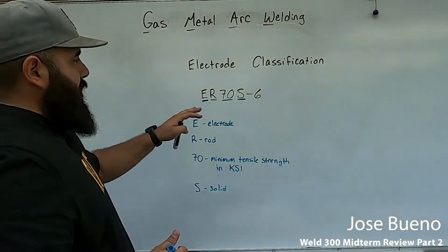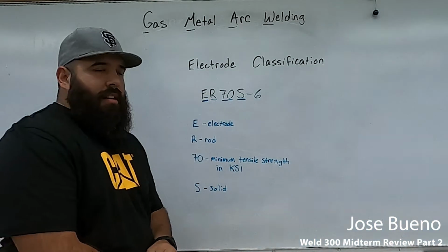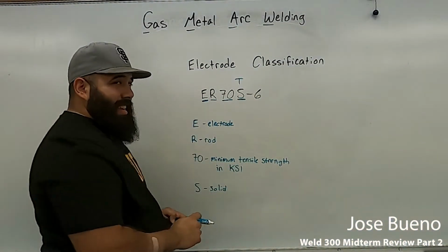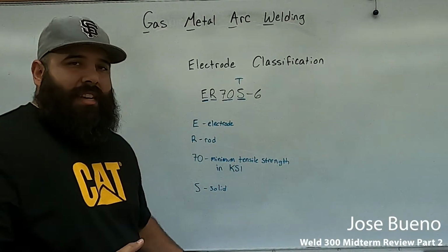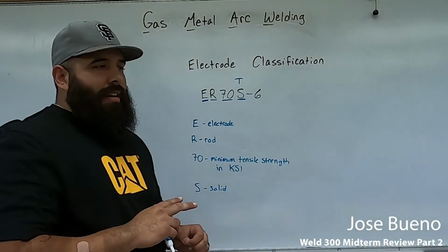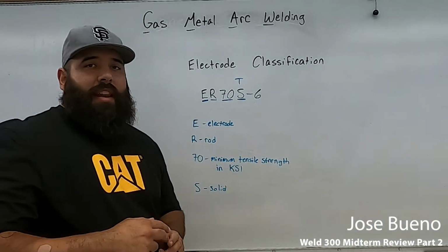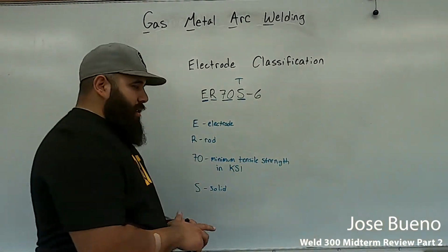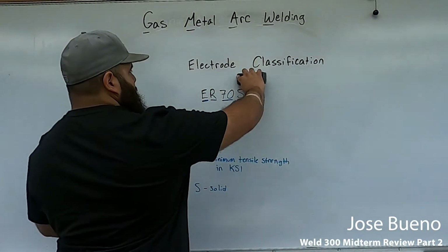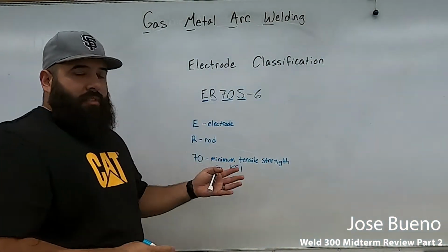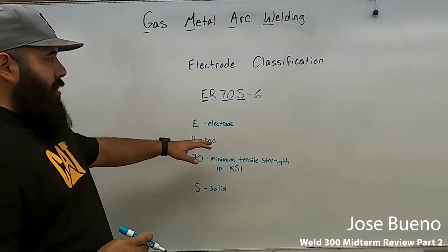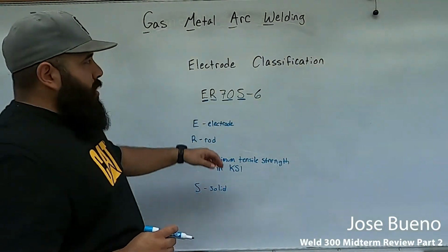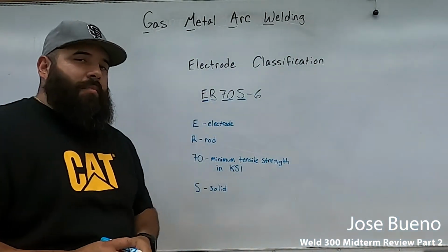You'll find different welding electrodes out there. In place of the S, you could see something like a T. If you see something with a T, that means when you cut the wired electrode, you'll see that it's in fact tubular or hollow. There's going to be something in there. And you'll see some other electrodes out there with different letters in that place. But for now, just remember, if it's S, it's referring to solid, which leads us back to GMAW.